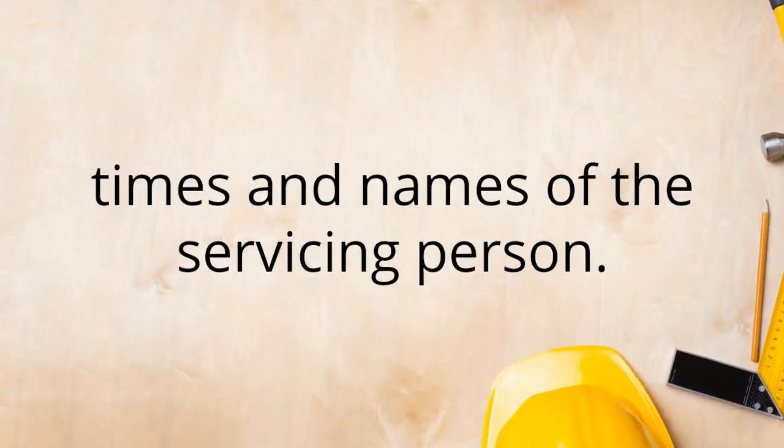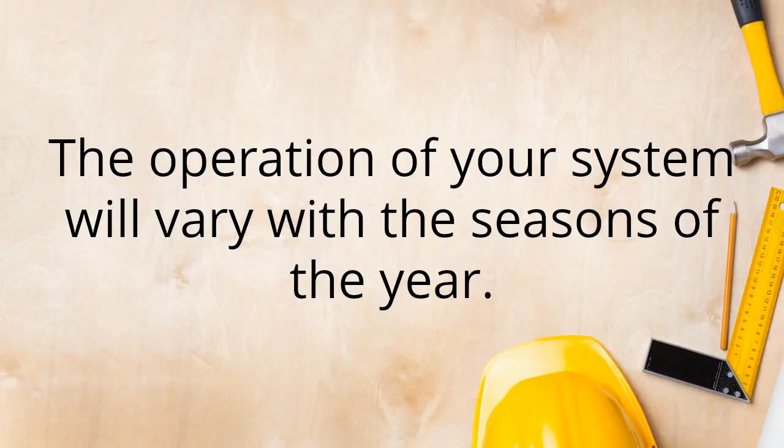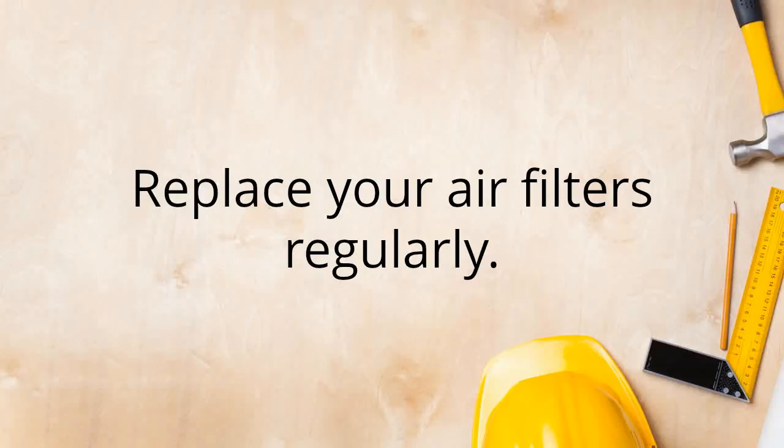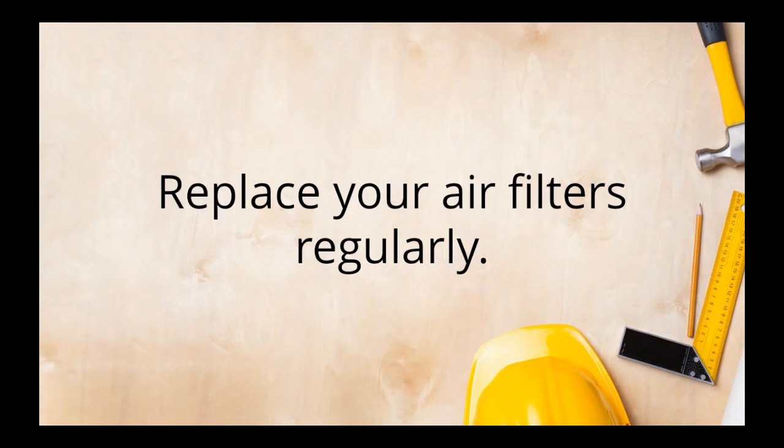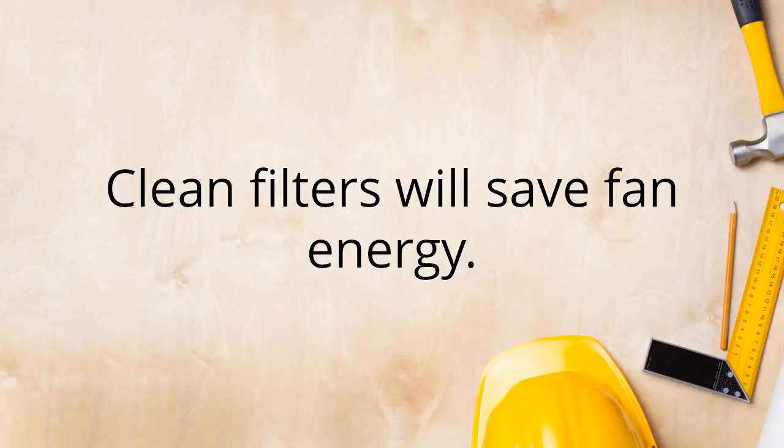Homeowners should always get a seasonal tune-up. The operation of your system will vary with the seasons of the year. Replace your air filters regularly. Don't use anything less than a MERV 5 filter to assure dust and fibers are removed. Clean filters will save fan energy.